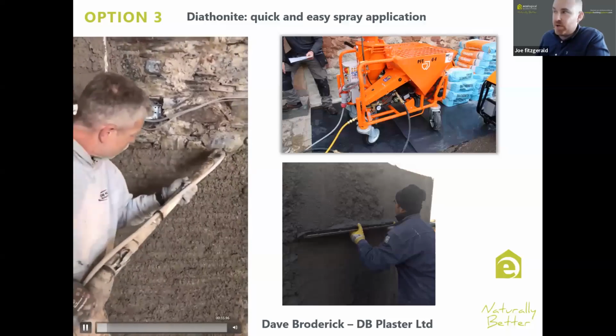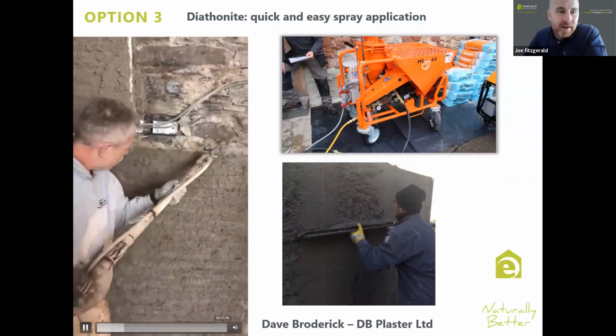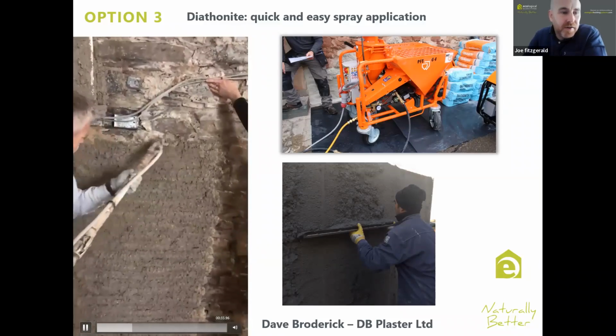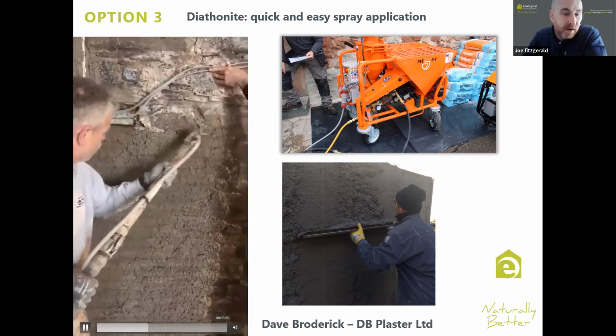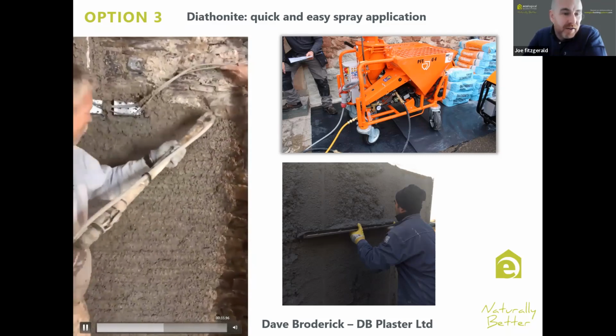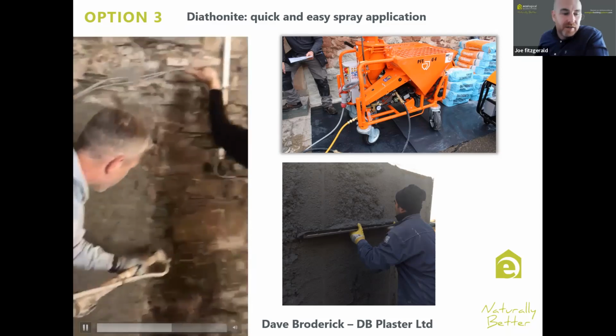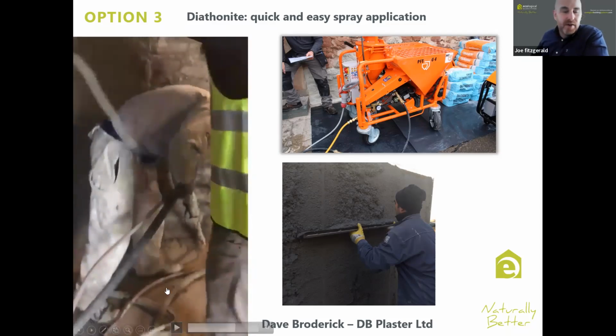I'm not going to show too much of this, but one of the advantages is sequencing. You can get your electrical first fixing done and your conduits and things in place, and you can literally swallow them with thermal plaster, so long as you prepared everything in an adequate way. So in terms of sequencing, they're actually very advantageous as well. You do about 200 square meters in one day with a pump like that. So for large, old, exposed stone structures, they can be really useful.